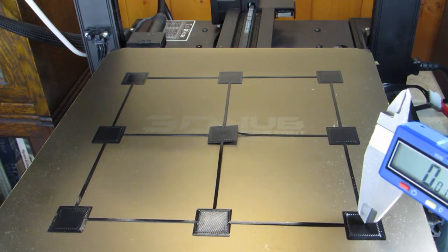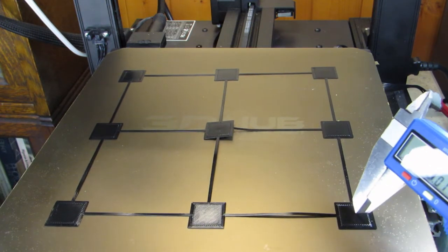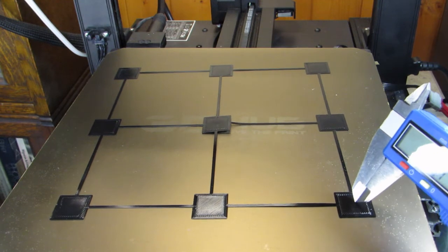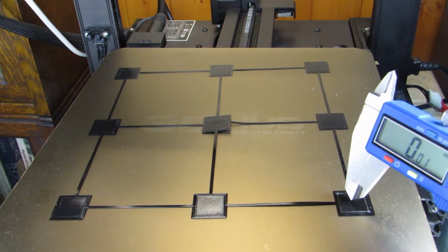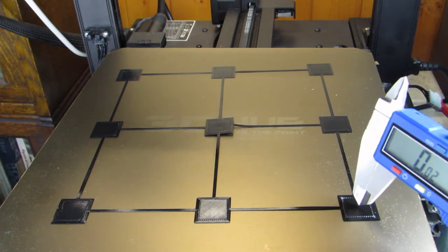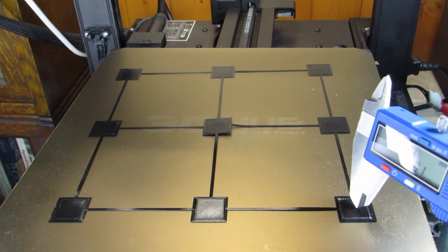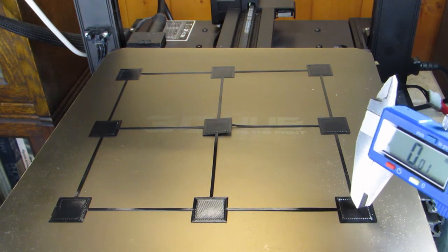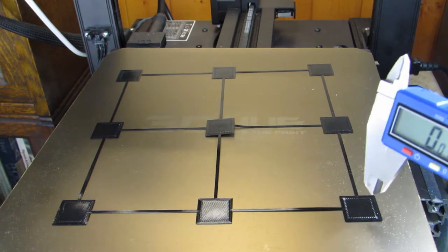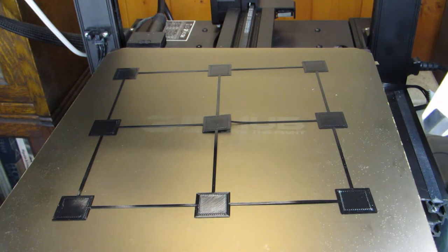I'm arguing really that there's a limit to how accurately you can set these points. There was a time when Creality was first selling these printers, they had the firmware set so that you could only change offset in 0.05 millimeter increments. Maybe they knew something that I'm still learning. But 0.2 is what I asked for. 0.24 seems to be what I got.